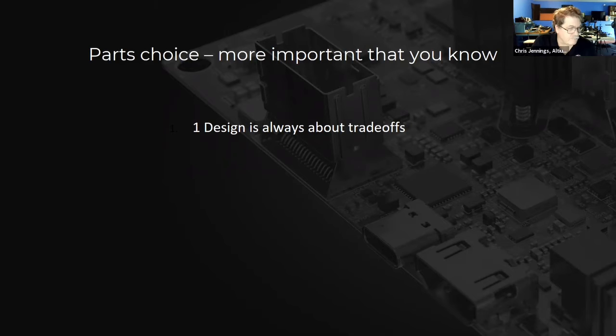It is a very large BGA package, which brings up the last point about parts and component selection for your schematic. Again, you need to be able to get this onto the board. This particular package, I can easily make the package footprint, but what I couldn't make was the 700 some odd pin schematic part. Nobody had it anywhere. I couldn't get it, so I'd have to create it by hand.